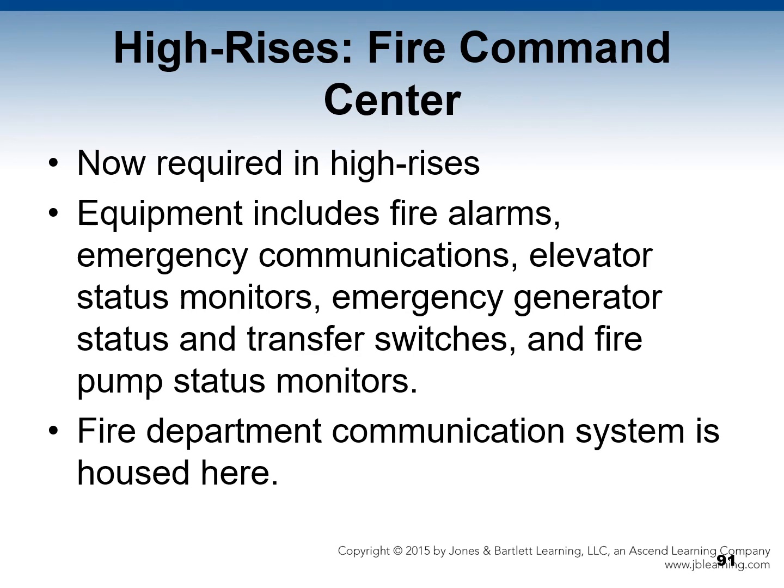With high-rises, let's talk about the Fire Command Center. Fire Command Centers are now required in high-rises. They're typically accessible from the lobby. Their equipment includes fire alarms, emergency communications, elevator shaft monitors, emergency generator status and transfer switches, and fire pump status monitors. The fire department communication system is also housed here. Post 9/11, there will typically be a radio signal amplifier.